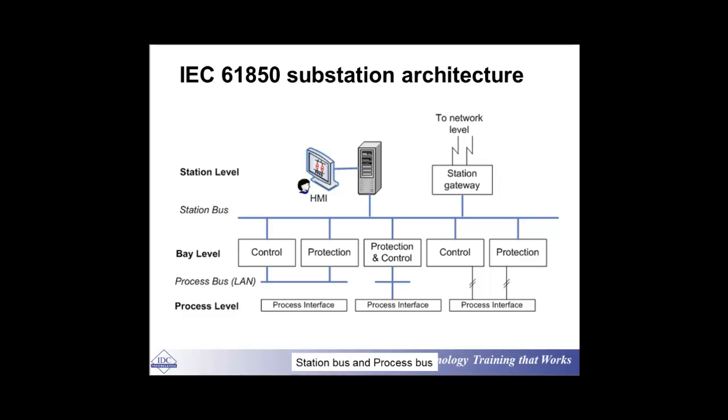So in this case, the process bus is a LAN, and also we have the station bus. This station bus can be connected to, let's say, a gateway, so that it can share the information via a network remotely with others. At the same time, you can directly connect your laptop or desktop computer to that station bus if you are an operator, a decision maker, an authorized person, and see the status of your system regarding all the pumps, tanks, conveyors, generators, motors, and transformers.